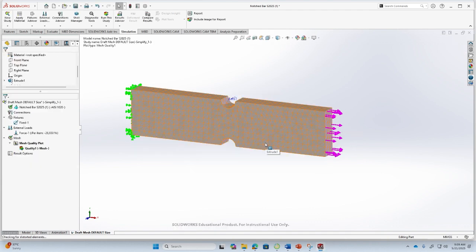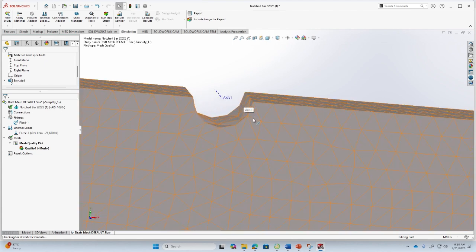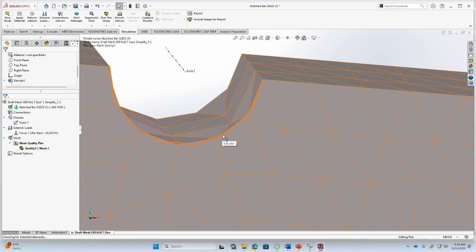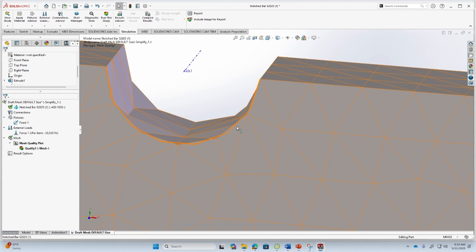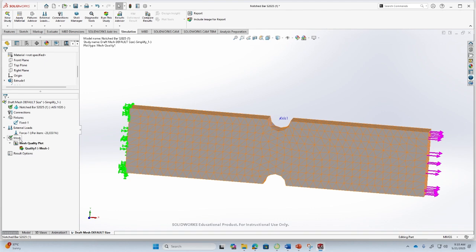So now as soon as I click OK, the software does a bit of processing and it does this discretization of the domain for you, and you can now see the whole part divided into these wedge-like elements, right? So you see all of these wedge-like elements, and they are here. And you can see here that because of these wedges, the circular face is slightly approximated, right? It's not exactly circular, but depending on, of course, the number of wedges that will be here, you can have a closer approximation.